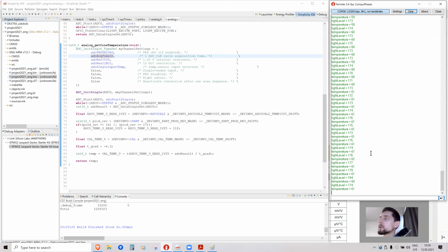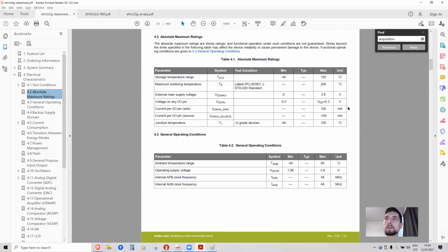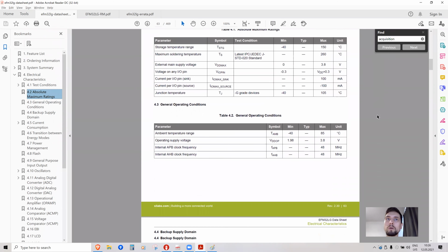But actually, if you look at the datasheet of these chips, you will see that the chips guarantee the temperature that it can survive in is only 85 degrees, right? In reality, if the chip is heated to 100 degrees, it might still work, but there's a risk that, within 1 year or 2 years, the chip will just malfunction and not work.